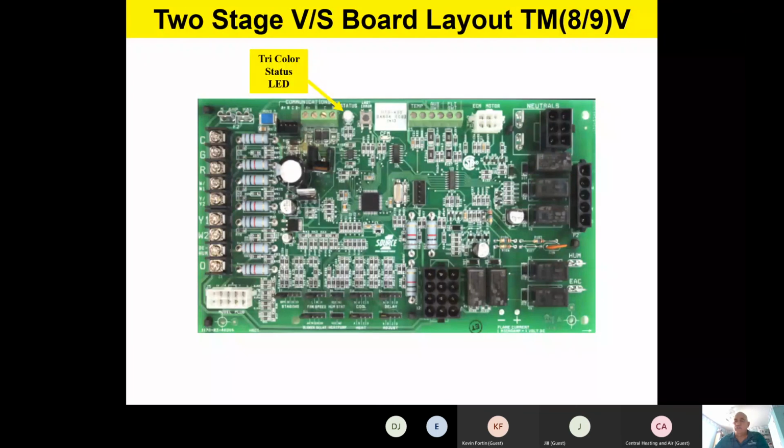It'll flash either red, yellow, or green based on the flash code. There's our last error button that works just like we did before. You can hold that last error button down for about 10 to 15 seconds and it will clear the memory. Or you can retrieve the flash codes by depressing it and watching the flash codes.